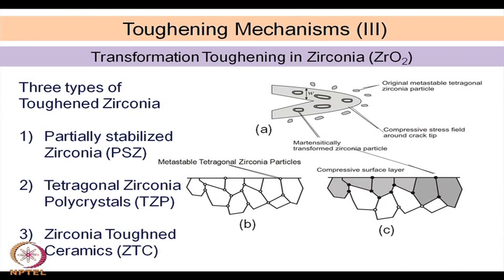So, that tetragonal phase is again thermodynamically unstable, and that tetragonal phase can be transformed to a monoclinic phase, a more stable form, through what you call the stress induced transformation. So, transformation here is a stress induced transformation. So, it is not the temperature alone, but the mechanical stress also can induce this transformation, and that is a peculiar characteristic, or very important characteristic, of this transformation.